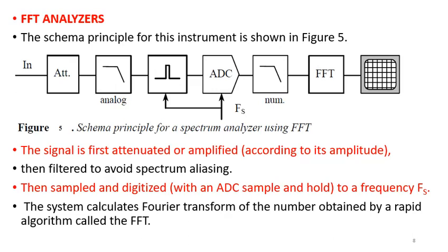As we know, the function of the filter is always to what? Remove certain range of frequencies that are not allowed, normally harmonics or overtones. Now after that, we go to the level of sampling, because in this one you have to change your analog signal into the digital form. And the first stage we do in changing analog signal to digital is to take samples. Taking the samples is normally done using what we call a sample and hold circuit, and this represents a sample and hold circuit.